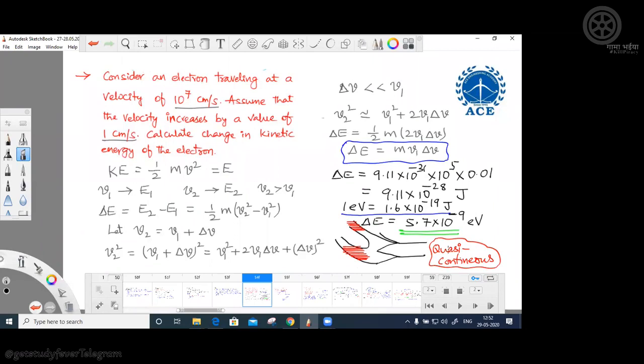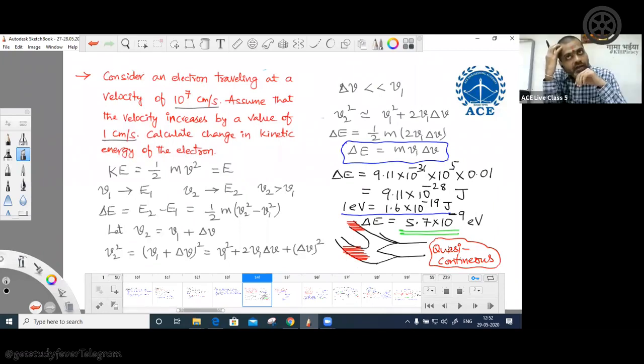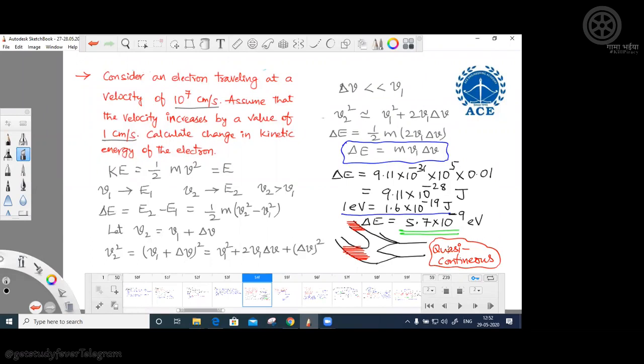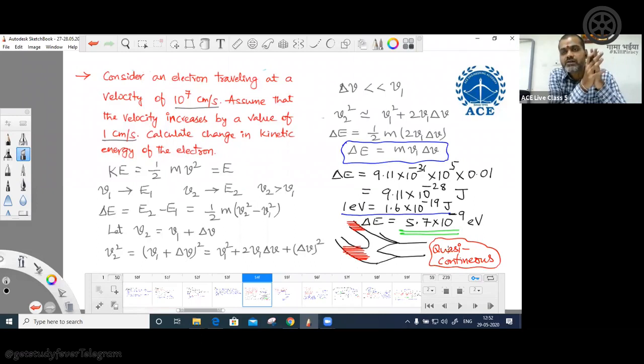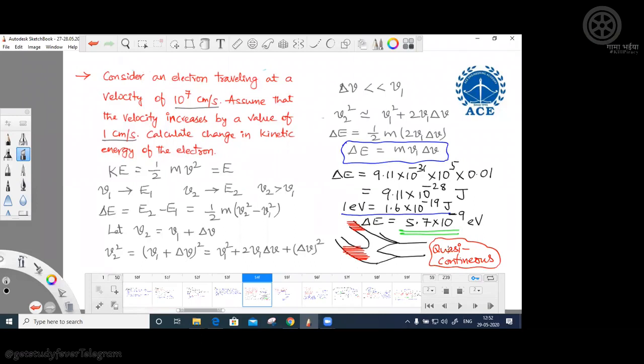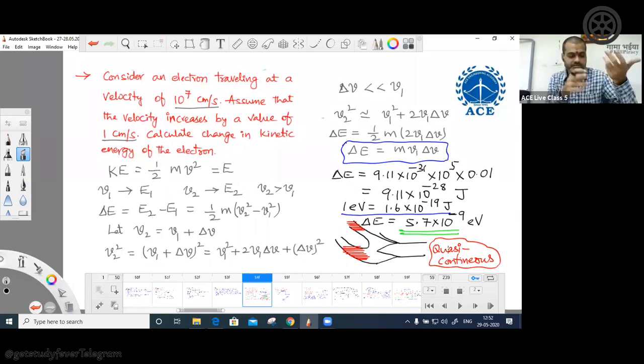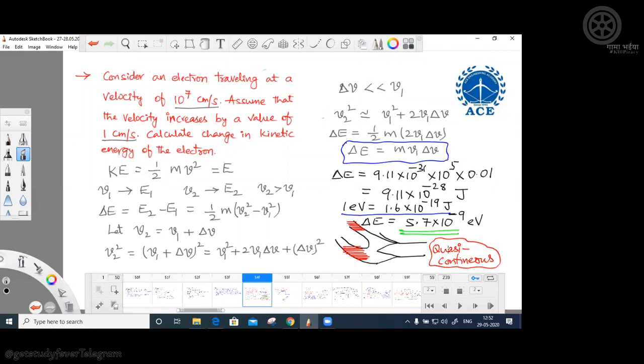Sir, and another doubt is, why are we considering only the concentration at the edges of CB, I mean, edges of conduction band or valence band? Suppose you move the electrons from valence band to conduction band, where can you move from first? From the top of valence band to the bottom of conduction band. That is nothing but what? Edges, no? Achha, so we'll consider only the first one. Yeah, that will be enough for us. Because when you go deep into the bands, things will change, and that is not required for us. Okay, sir.